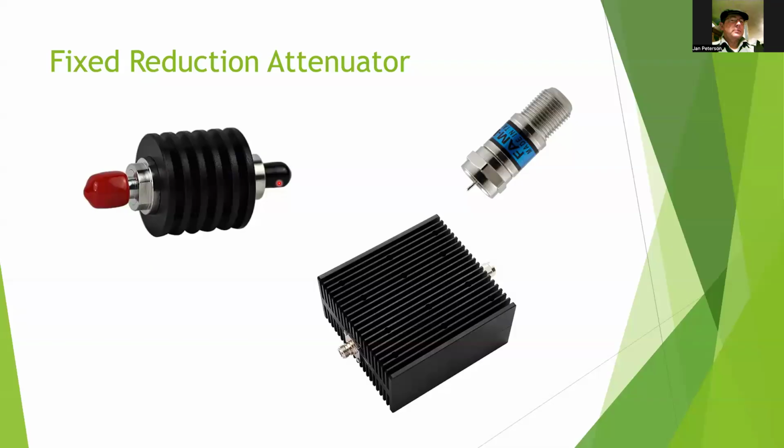Yes, if I put too much power into it, like this one is probably rated for, I want to say 10 watts. If I tried to dump 100 watts into that, it would probably damage it. And there's usually a chart that comes with them that says what you can do with it, showing power level and for how much time. So that one on the bottom can probably take 100 watts for 60 seconds. Or 5 watts indefinitely, for as long as I want to pump it in there, right?